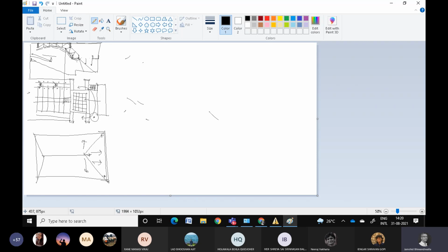So levels, material and levels that is expected. The schedule at the roof plan will actually talk about the roof covering that is there. Number of people show the dotted girders. Some people show a part plan with the purlins that are there and the sheeting that is there. So some people show the roof in 3 parts. One is they show the position of the main trusses or the girders, then show the purlins on top of it and then the sheeting.